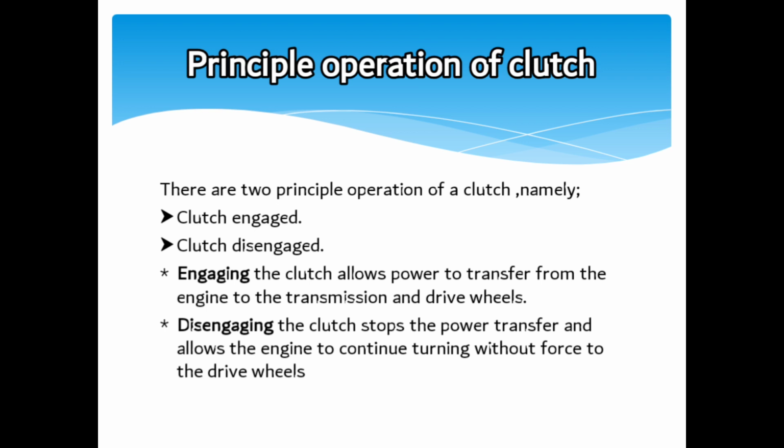And on the other hand, to engage the clutch, as earlier, the clutch pedal is released and the release bearing moves away from the pressure plate. This action allows the pressure plate spring to force against the clutch disc, engaging the clutch to the flywheel. Once the clutch is fully engaged, the release bearing is normally stationary and does not rotate with the pressure plate.